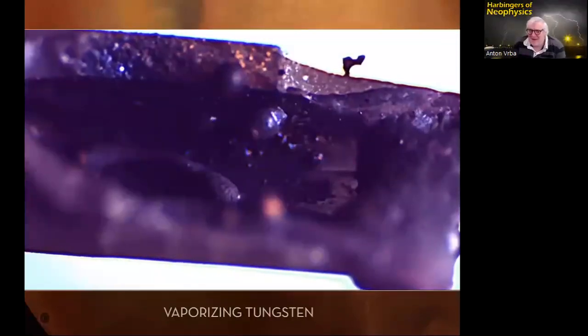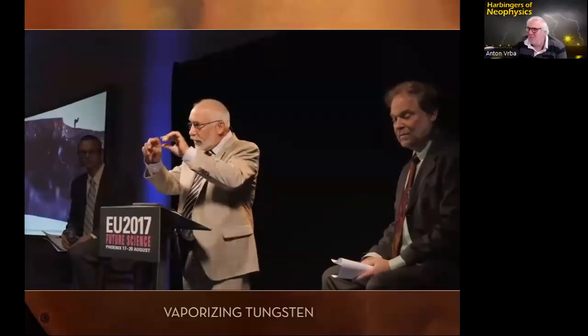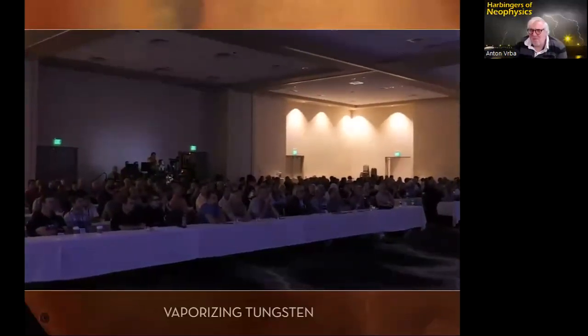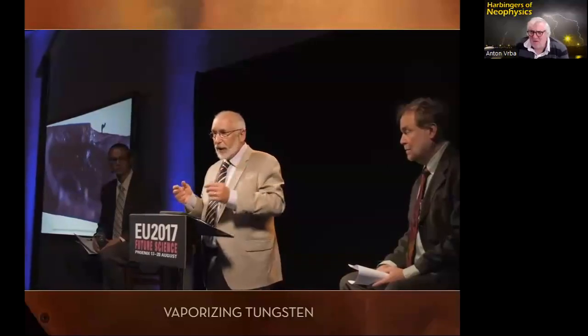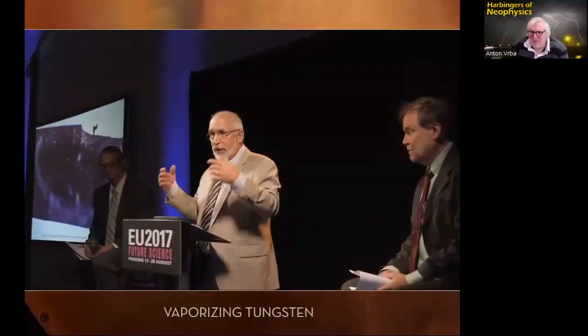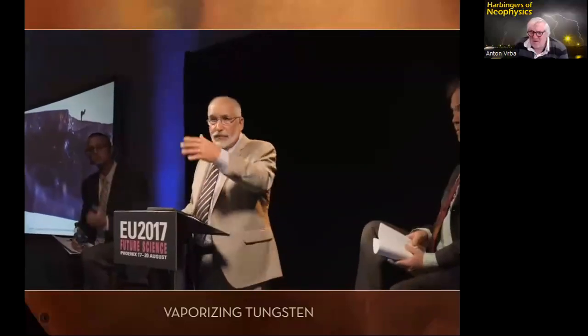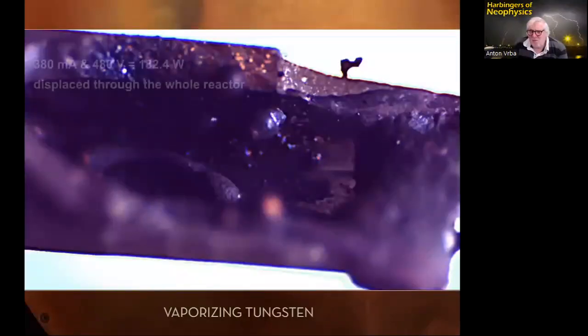So when we opened up Sapphire, we discovered what was left. This is what the tip looked like after it vaporized; this is just the residual tungsten you see here on that kind of nodule. That's what was left of it. Anyone who knows anything about tungsten knows it takes about 6,600 degrees Celsius to boil it. To vaporize it, you need more energy, and in thermodynamics, as some of you probably already know, there's a time domain associated with it and how much heat is lost in the system as well. So it's not just 6,600 degrees. If you're going to vaporize it that quick, it would typically point to temperatures much higher than that, and not the 2,300 degrees we predicted, because the tungsten should have heated up, might have started glowing a little bit, but it should have lived in there. Well, obviously, it didn't.